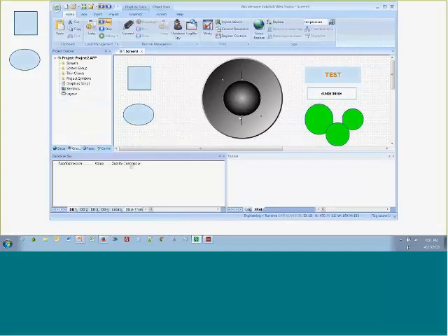If you have an object selected, if you look down here in the status bar, there's an ID number. If you didn't know, that ID number is the Z layer, from rearmost to frontmost, the kind of object ID in order from the rearmost, so the biggest circle there is the rearmost object. The second circle is ID number 1, so it's the second layer, and so on and so forth. So every object on the screen has a unique layer, or a group of objects has a unique layer associated with it.